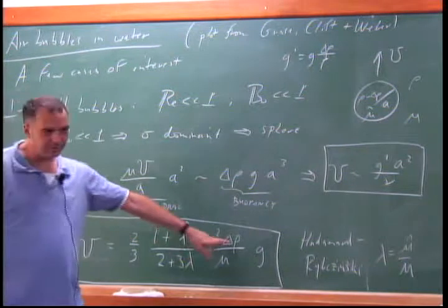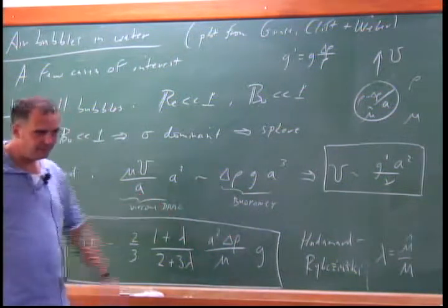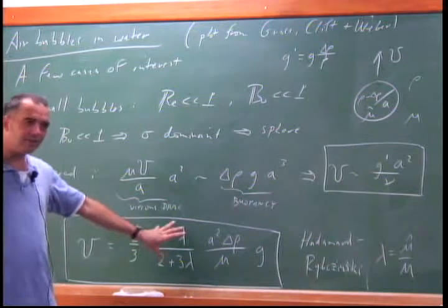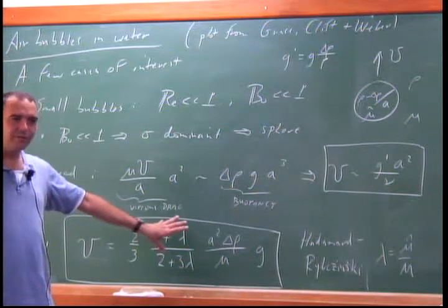Okay, so there's a very small difference between the rise speed of a bubble and a rigid object. Of course, you have to non-dimensionalize. You have delta rho in there still. But you see that this dependence on viscosity, internal viscosity, is very weak.